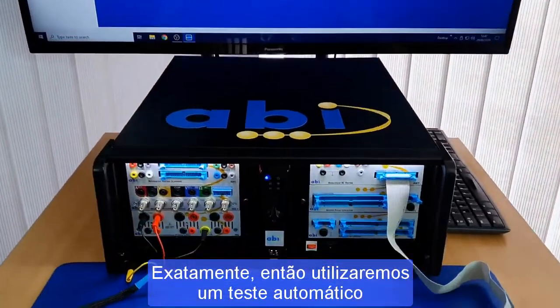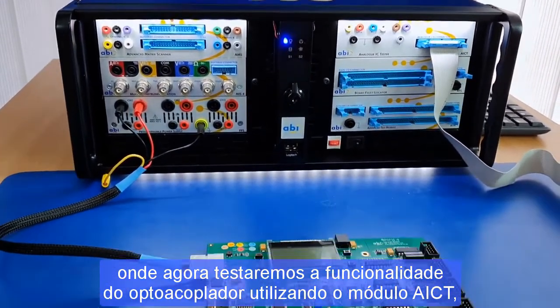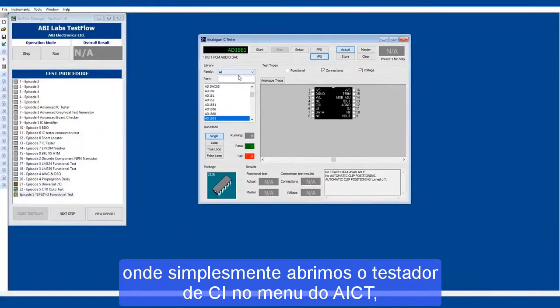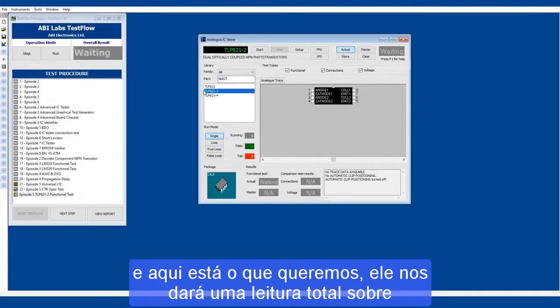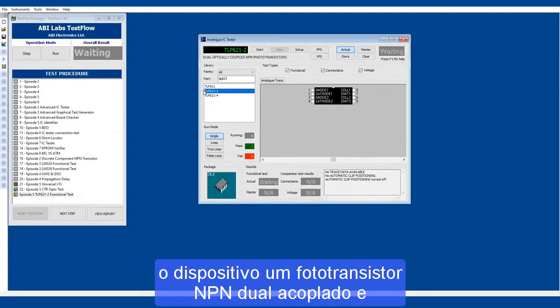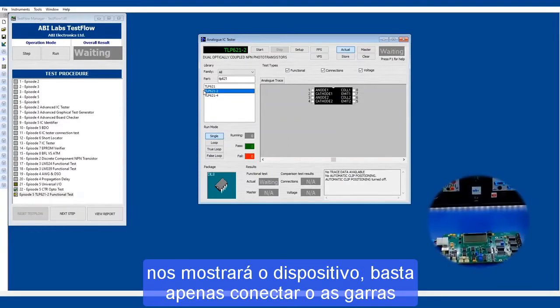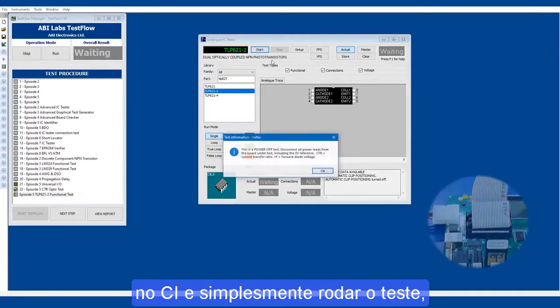Exactly. So using more of an automatic test, we'll now test the functionality of the optocoupler using the AICT module, which is as simple as opening up the analog IC tester in the AICT module, searching for our device, which is a TLP621. And there it is. This is the one we want, and it gives us a handy readout about the device, a dual coupled NPN phototransistor. And it gives us that DIL package. That's our IC there. Just need to hook onto the IC, as simple as that, and run the test.